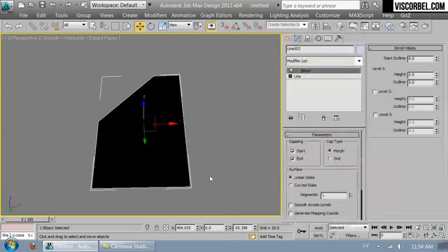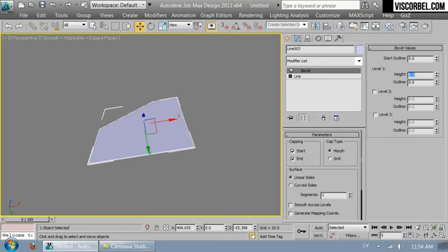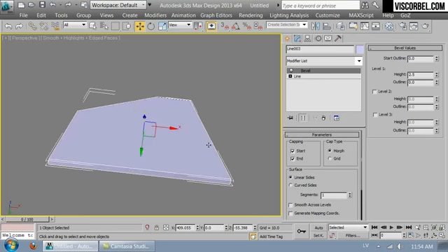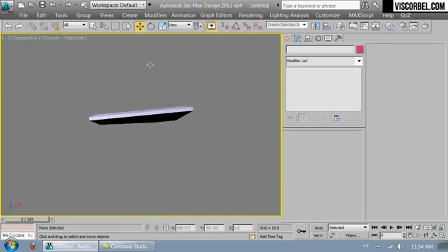What it does is it allows you to extrude the line in multiple steps. For example, you first extrude it 2 centimeters up, and then add a second level, extrude another 2 centimeters and outline, let's say, -5 centimeters, and you have this beveled shape ready to use.